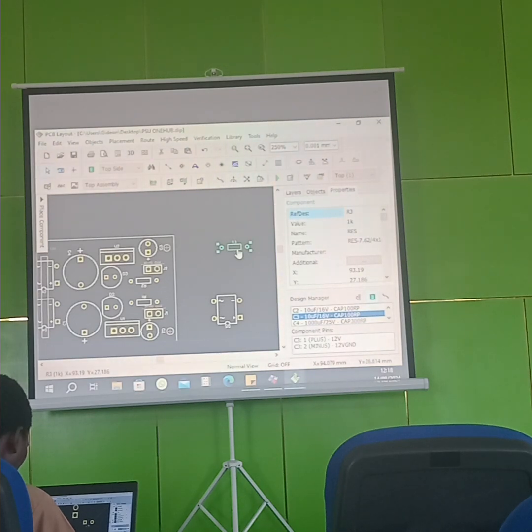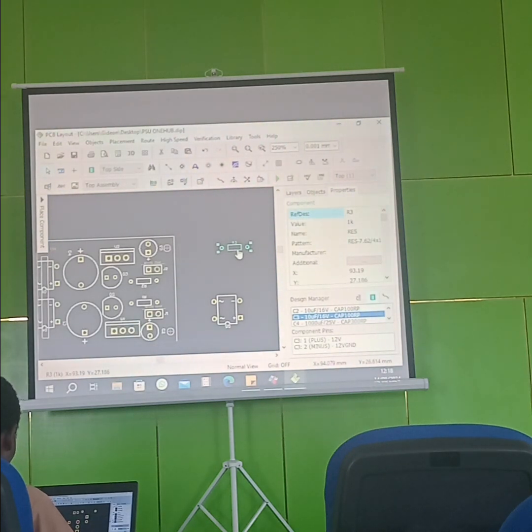Because I've operated pick and place machine very well. Optimization, so that the machine will pick and place all those components faster. Any component without polarity, we make sure that it doesn't stress the nozzle. Have you seen a pick and place machine before? The one we have has 8 nozzles. It's 8 components at the same time. It uses air pressure to suck the component from the component feeder. Once it sucks it, it places it on the board at the same time.